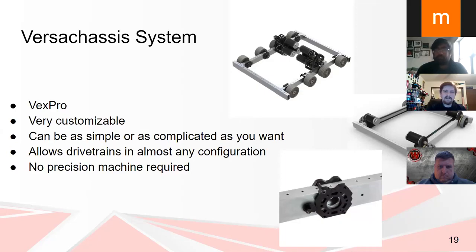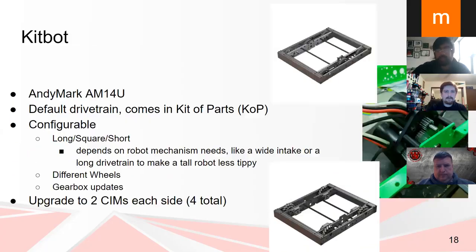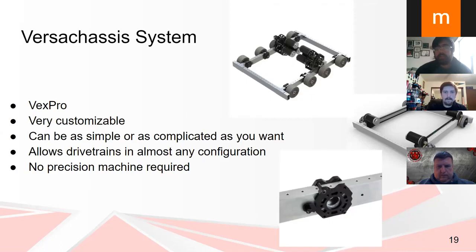Is there anything else that's characteristic of a West Coast that I missed? Not particularly. People might have questions about why those wheels are cantilevered, and we can obviously talk about questions again at the end. But they're cantilevered for ease of maintenance is probably the biggest strength. You can just pull your wheel right off instead of, in the case of something like another design, you've got to take some stuff off. You guys can see that they're surrounded on both sides. Each has their strengths and weaknesses, and I don't think one is inherently always better than the other.